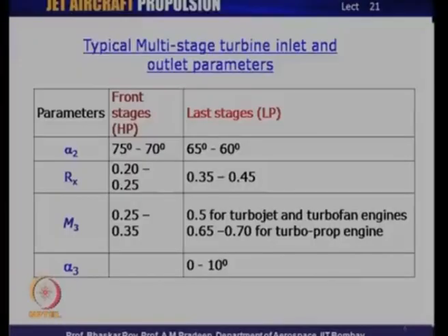On the other hand, in the last stages, the flow may or may not be sonic, and the angle is slightly on the lower side, corresponding to the exit flow condition from the stator nozzle of that particular stage. The degree of reaction R x in turbines, as we know, is typically on the lower side compared to what you may have seen in the compressors. The degree of reaction in turbines is substantially lower, which means that more of the static changes are occurring in the stator and less of them in the rotor, and this is by design.